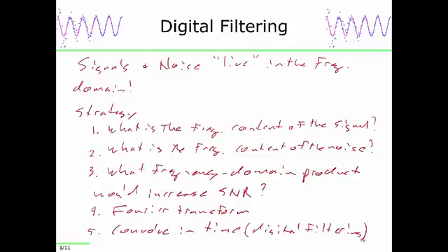The advantage of doing digital filtering is that the vectors that you're multiplying don't have to be the same length. In other words, I can have a 5-element filter and a 10,000 element data set, and I have no problem with digital filtering, but doing the Fourier transforming and multiplying is a little more inconvenient. But in principle, you absolutely can do either one of these. In practice, there are advantages for doing digital filtering when your filter is small relative to the data set. Excellent question. Okay. Let's do an example.